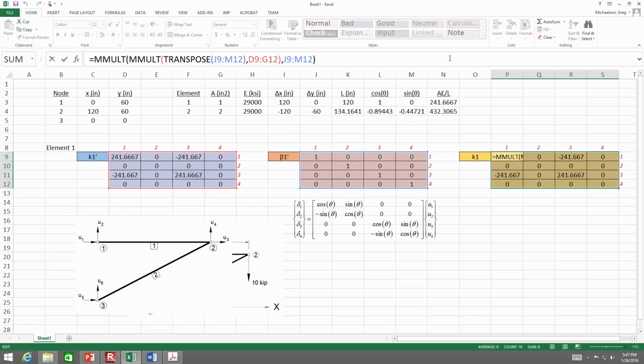But to do this, it doesn't take any force at all. So that's why that particular value is 0, and all the associated values are 0 when it comes to moving that joint this way. Only that way do I actually have to overcome something. That's because I'm dealing with trusses. If it was beams, it'd be a different story.